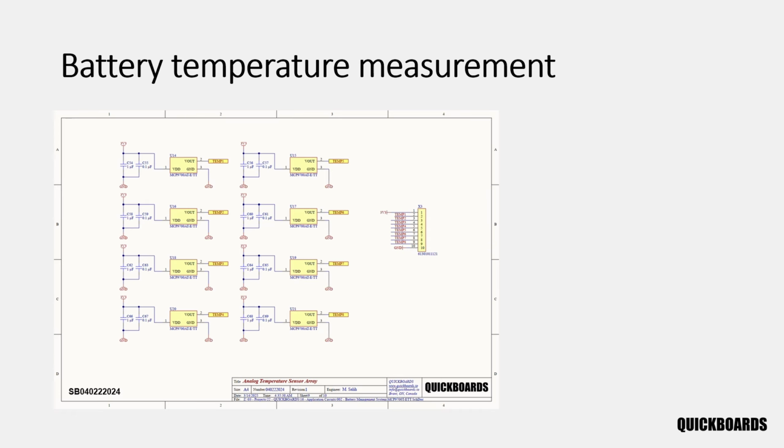However, in many real-world applications, the battery pack is physically separate from the BMS circuit. In those cases, NTC thermistors or thermocouples are typically attached to the battery cells, then connected to the BMS board through a cable and connector.